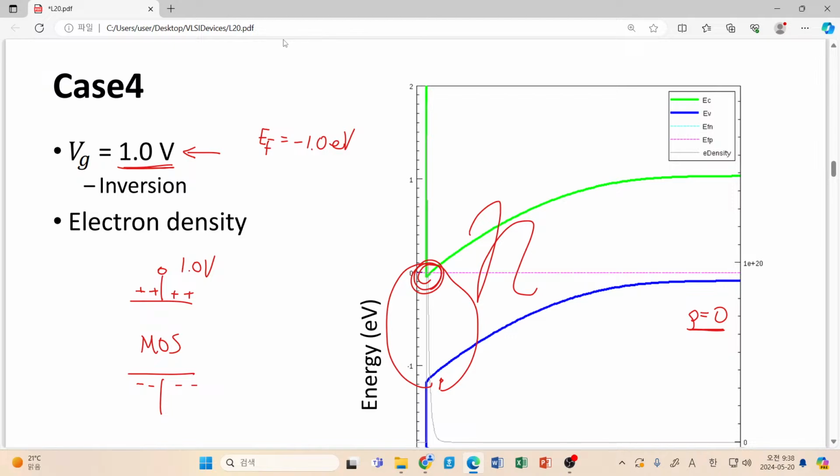Yes, that's true, but this negative charge now originates not just from the depletion layer, but also from another contribution from electrons. Once again, this depletion corresponds to acceptors. These are immobile. They do not move, they just stay there. Impurities are heavy and sit inside the silicon lattice, and they do not move. However, additional negative charge is supplied from our electron density.